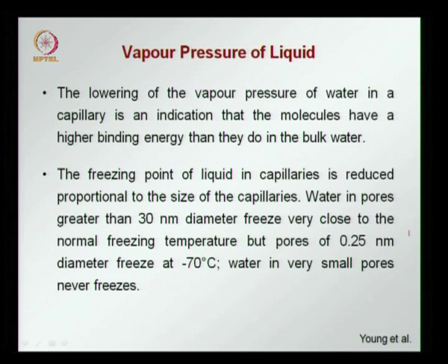That is, water in very small pores never freezes, and this is important when we look at freeze thaw damage in concrete and other materials, where we have the movement of water as the temperature is dropping. Not all the water freezes suddenly at the same temperature, but water in larger pores freezes first and then the smaller pores and so on. So, this freezing water moves and creates a lot of stresses in the capillaries which eventually lead to cracking and damage.